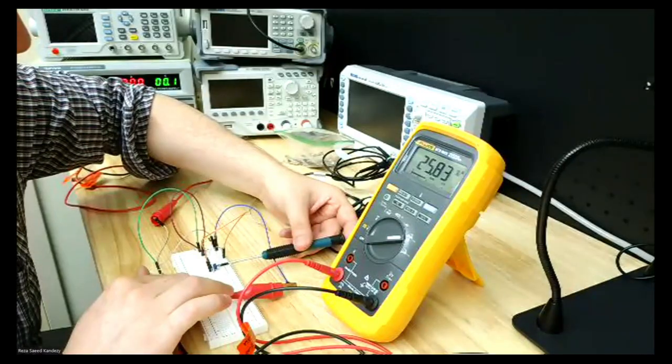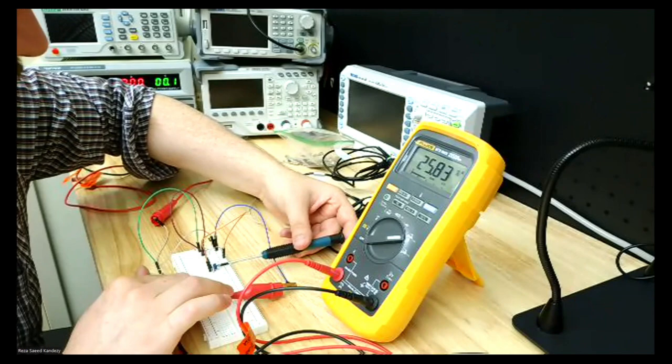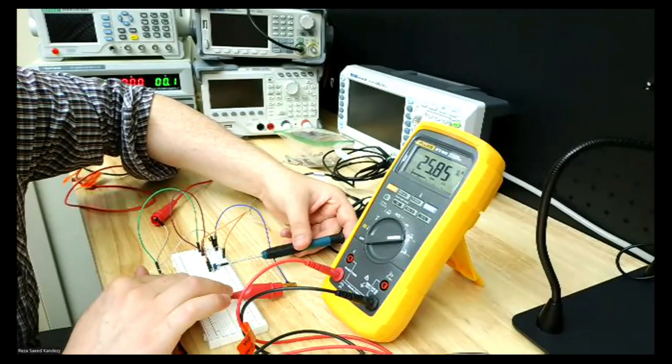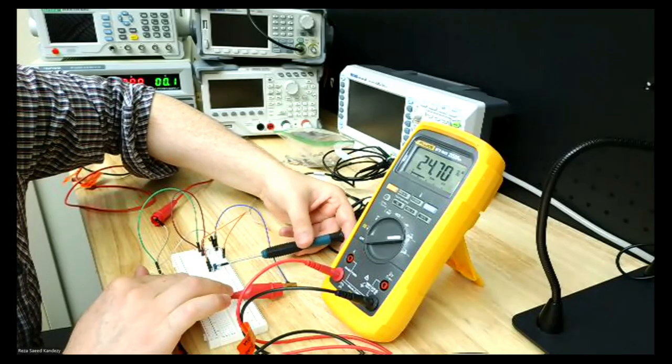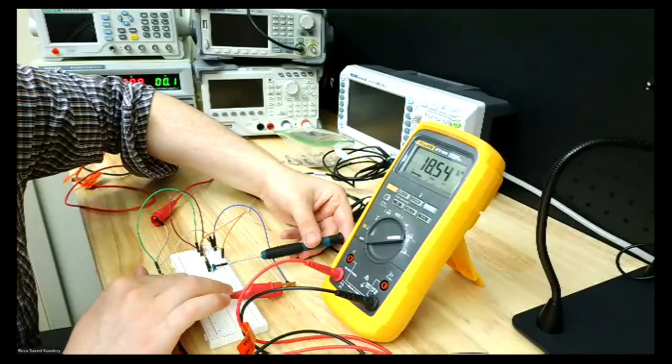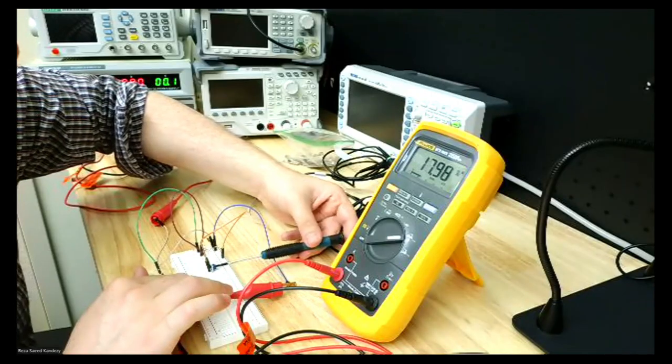The Zener diode is not exactly what it should be in theory, the resistances are not the same, and the potentiometer is not the same. So we need to apply a little bit of correction factor to make sure we are not exceeding the value of our maximum current. You can see that when I change the value of the load, the current changes, but the voltage stays the same, around 4.7 volts.